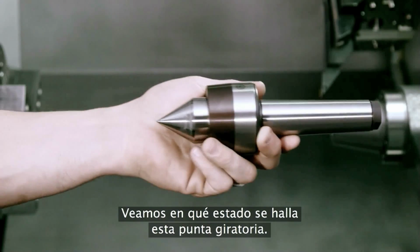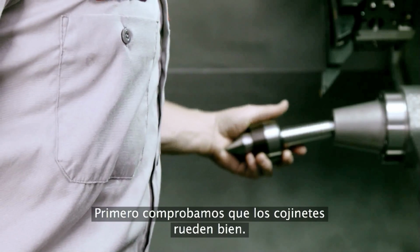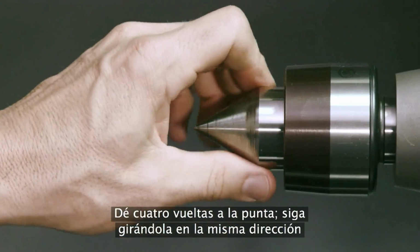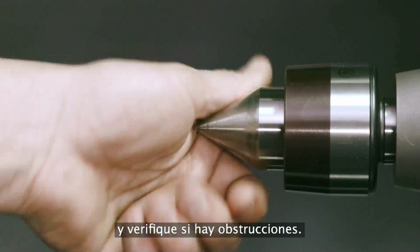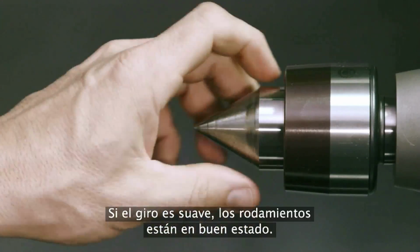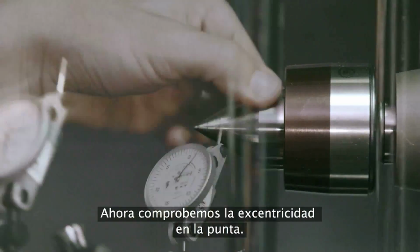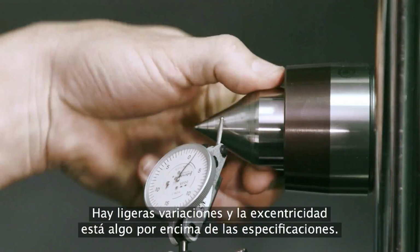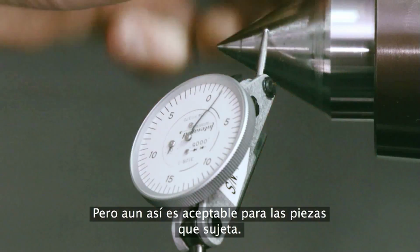Let's check the condition of this used center. First, we're going to check out how smoothly the bearings roll. Rotate the tip 4 revolutions, and then keep rotating in that same direction, feeling for smoothness of rotation. If it's smooth, the bearings are likely in good condition. Next, let's check the runout at the tip. The reading is a little jumpy and it's above this live center's specifications, but it's still acceptable for the parts it's supporting.